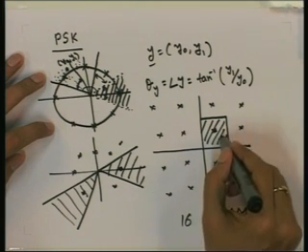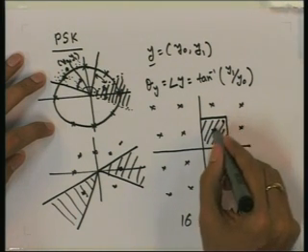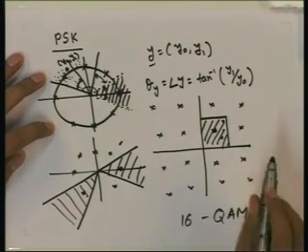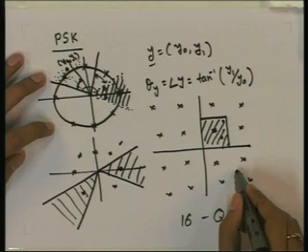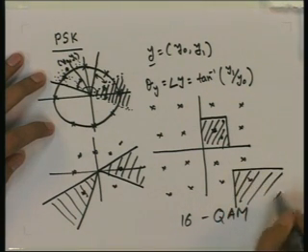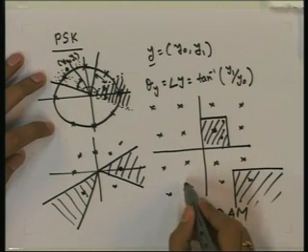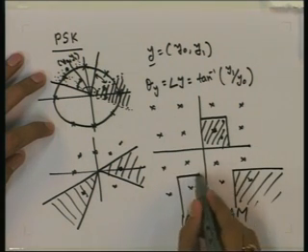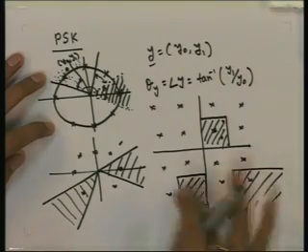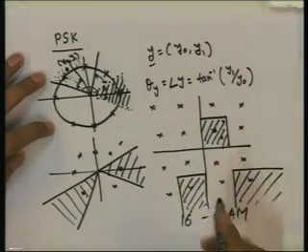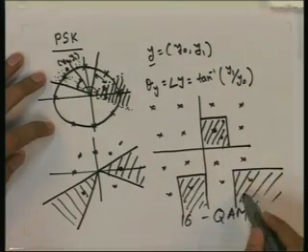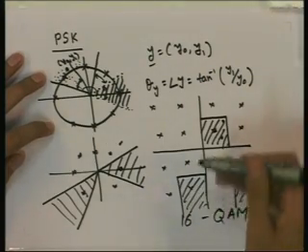This is further from here, so this is nearest. Even if it is here, this is the nearest point. So, all these points are nearest to this. Okay. Similarly, decision region of this point is this infinite region. Decision region of this point is this infinite region. So, there are three kinds of shapes of decision regions for 16 QAM. One is square closed, one is semi-infinite in one direction. Here it is semi-infinite in both directions.